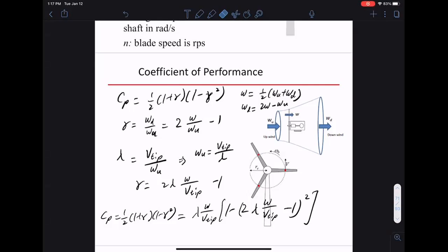Put a sensor in front of the turbine, you can measure it. You need the wind speed at your turbine, which presumably you can measure. Right, from that you can compute CP. Okay, so that saves you another measurement downwind. You don't need to go and measure downwind somehow.